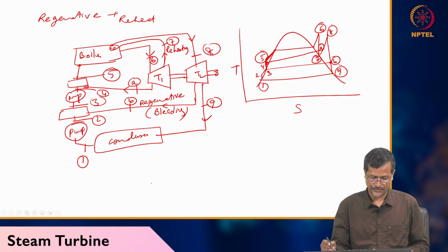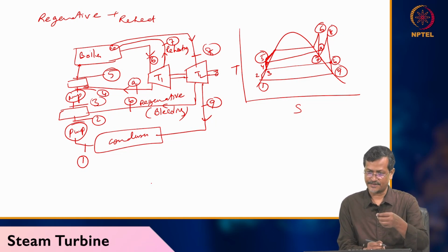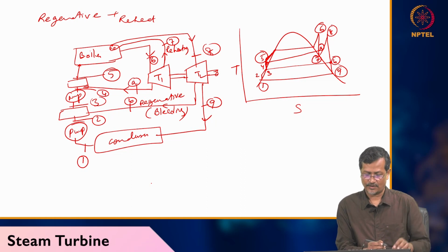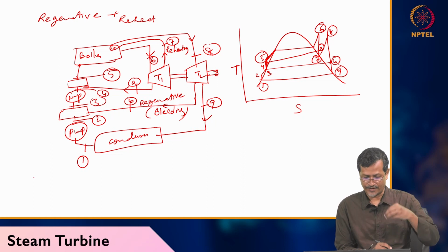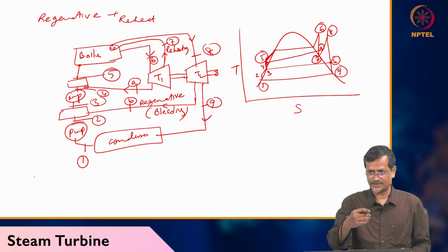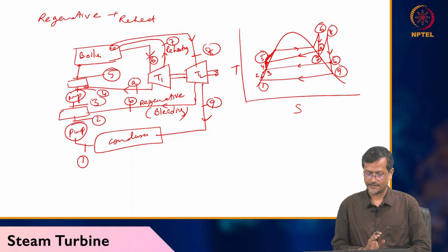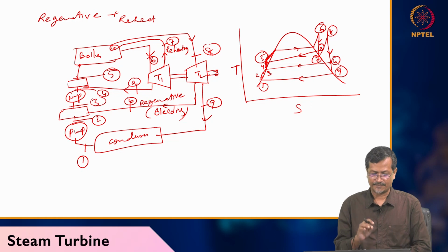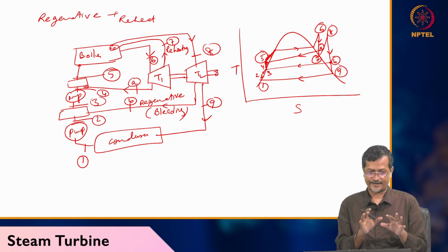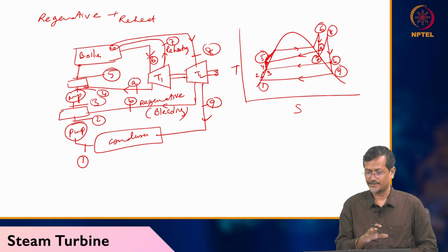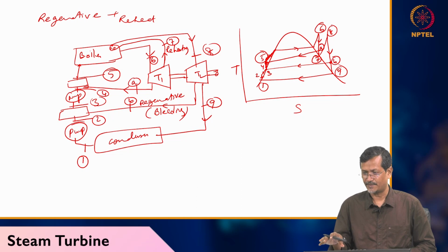This is very complex actually. Every turbine is giving some bleeding steam to increase the temperature of the feed water. Feed water means the water going to the boiler, from the condenser to the boiler. When you supply that steam, you are increasing the temperature using your bleeding steam. Whenever you draw this sort of diagram, put a proper arrow diagram and proper numbering, with the numbering matching on the left side and right side. Whatever line diagram I have drawn and whatever TS diagram is there, the numbers must match. If there is any mistake in the numbers, you will not get the marks.